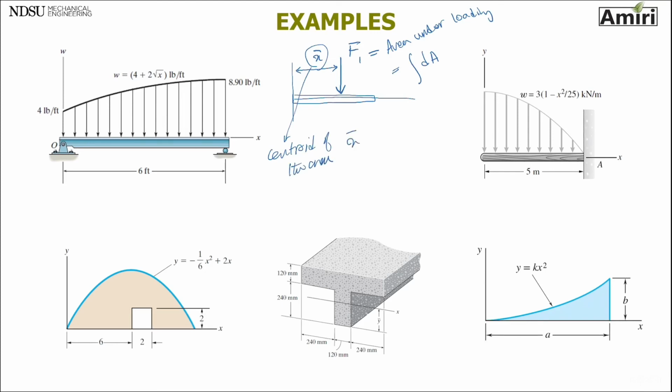which we have to find using that equation, x tilde dA over the integral of dA. Same thing with the one on the right side. So that's why once you know how to find the centroid, then you can do any distributed load equation, get rid of the distributed load, and put it as a single concentrated force.